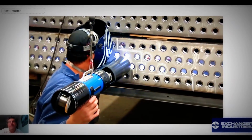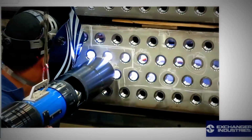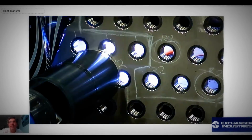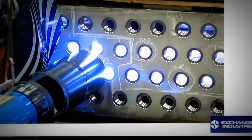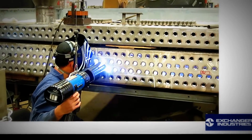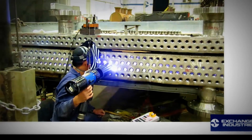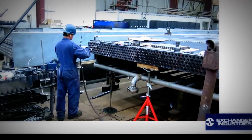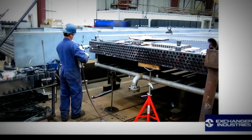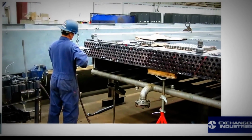And so here we can see a procedure whereby the tubes are being welded to the header box on the inside. And so this is a special welder that can go in and do a circular weld on the tube inside of the header box, and a very skilled practice in order to do that welding. As you can see, this welder performing the practice there, and sometimes the tubes are expanded, and so here we have a tube expander, pneumatic driven, and each of the tubes inside of the header box is expanded, and that's the way that it is connected.